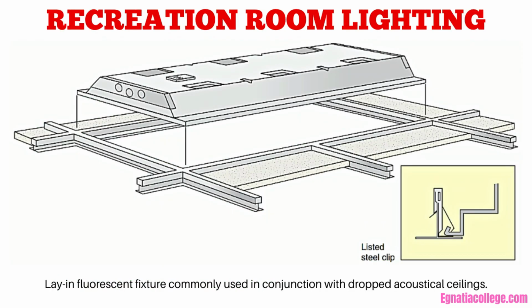Recreation room lighting. The recreation room ceiling is finished with 13 mm gypsum board. 6 lay-in 600 mm by 1200 mm fluorescent fixtures are installed into 600 mm by 1200 mm plaster frames that are fastened to the ceiling's framing. The fixtures rest inside of the plaster frames.